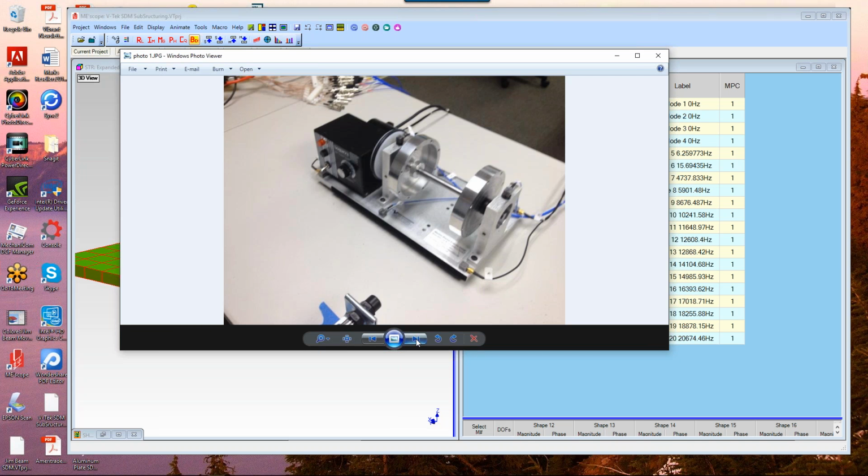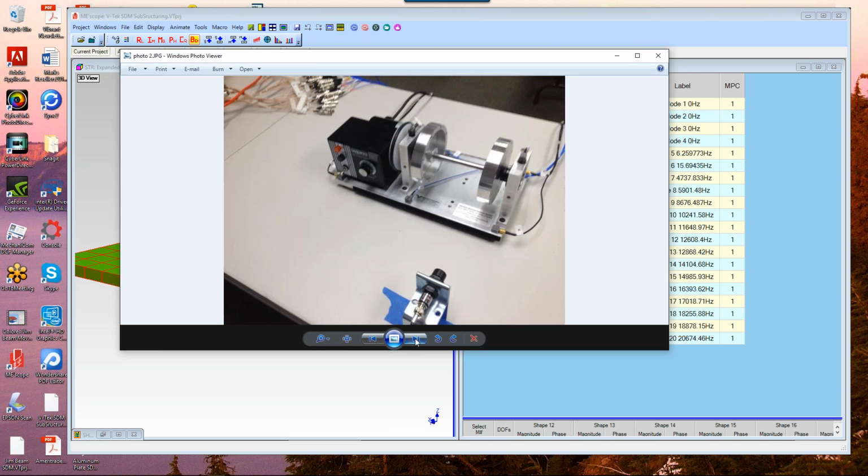In this picture there's 6 on the base plate and 1 on each bearing block. So there is what, 8 times 3, there's 24 channels of data being acquired. And down here actually there's 25 because we've got a tachometer, which is measuring the RPM of this machine.